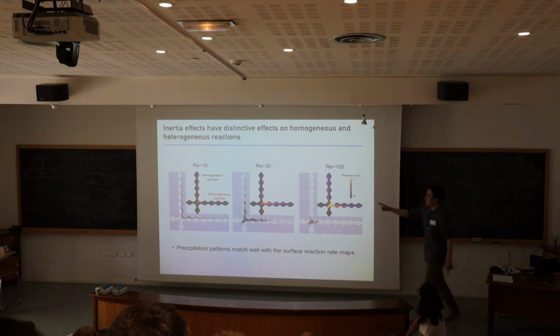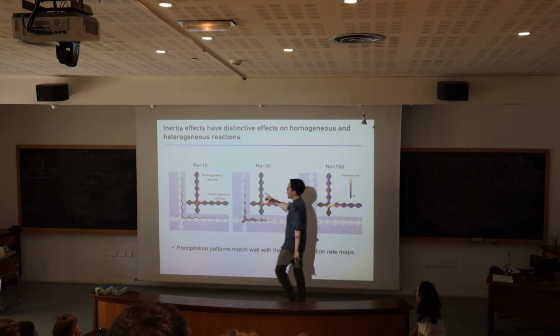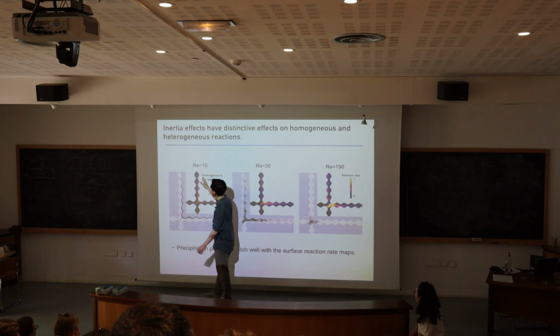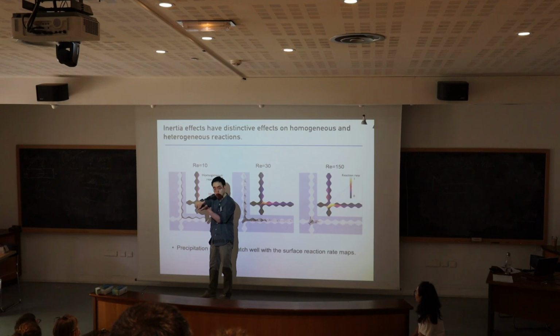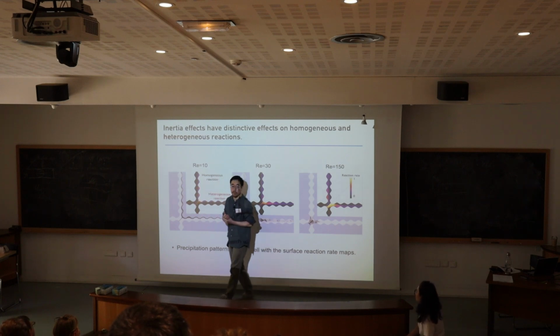What I didn't show here is that at Reynolds 1 to Reynolds 10, we see a similar transition. It's more diffused, and then it becomes thinner. The specific Reynolds number when it occurs is different, but still the effect that I showed, where the band decreases, is still occurring.